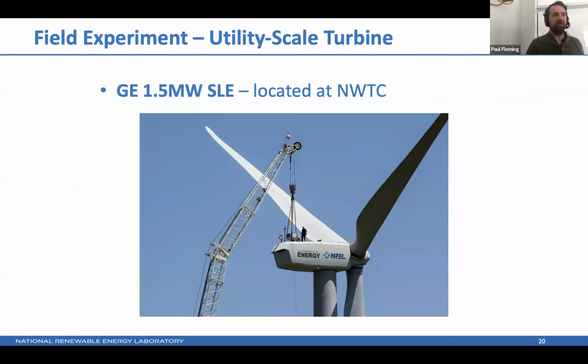Okay. Following that test on one turbine, we were able to graduate to doing tests on multiple turbines, with turbines in their wake. So this gives us an opportunity to actually do wake steering for a benefit. So taking one turbine and having it do its wake steering to benefit another turbine.